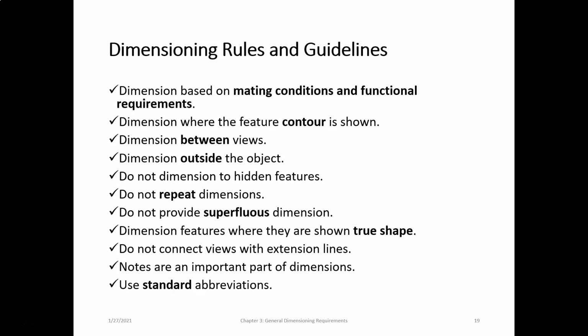Dimensions based on mating conditions and functional requirements. Dimension where the feature contour is shown. Dimension between views, right? Top view, front view, dimension between views. This does not mean connect dimensions between views. It just means place dimensions between views.